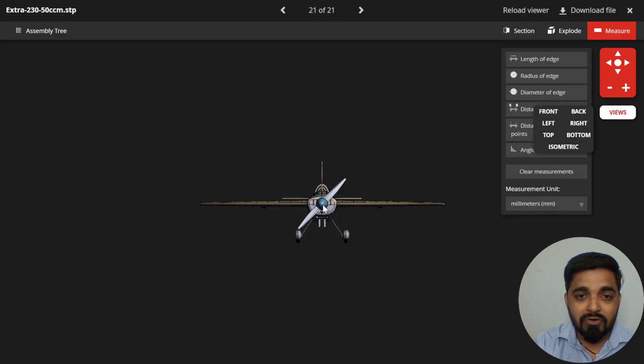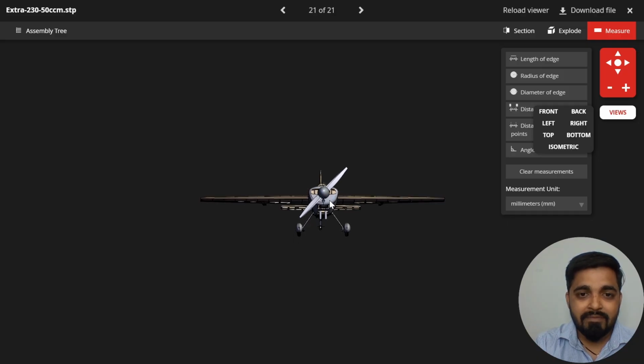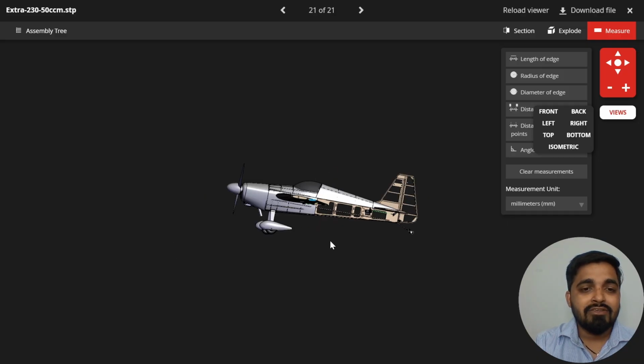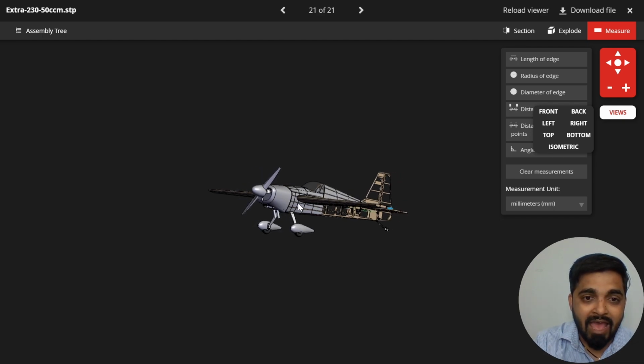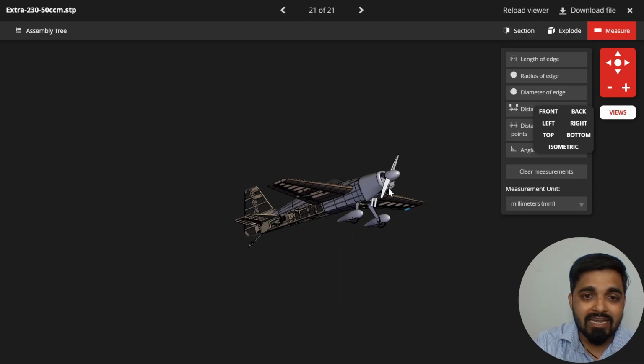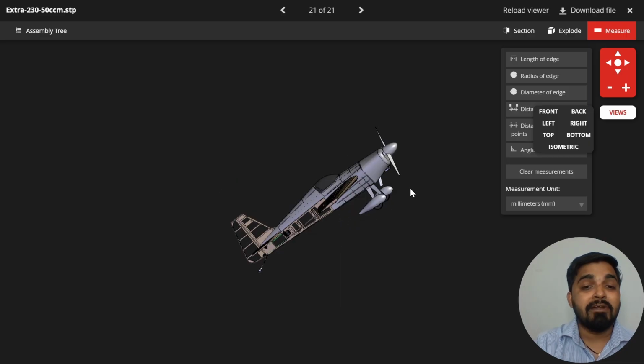When I tilt the nose of the aircraft a little bit up, you can see the changing angle between the relative wind and the chord line, and that changing angle is called angle of attack. But when the same angle has been increased this much, this particular situation is called a stall. So what's a stall?